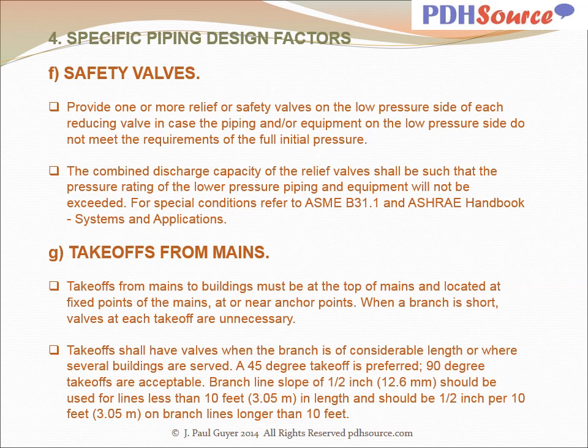A 45-degree takeoff is preferred. 90-degree takeoffs are acceptable. Branch line slope of 1/2 inch should be used for lines less than 10 feet in length and should be 1/2 inch per 10 feet on branch lines longer than 10 feet.